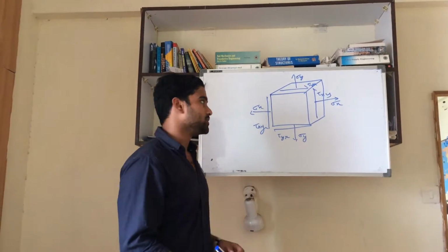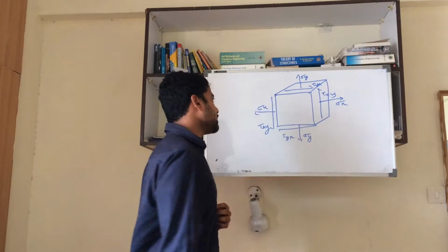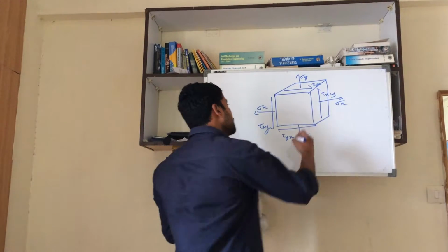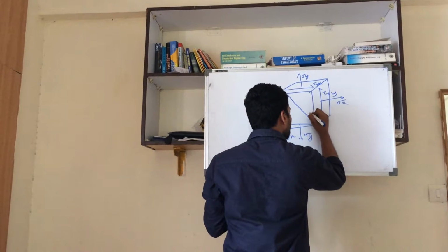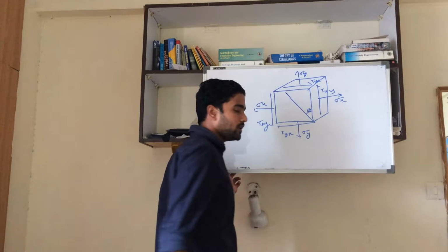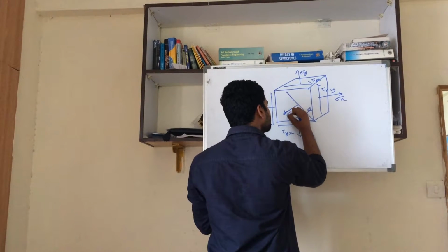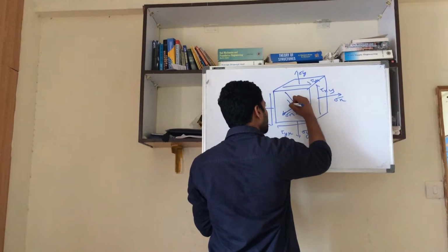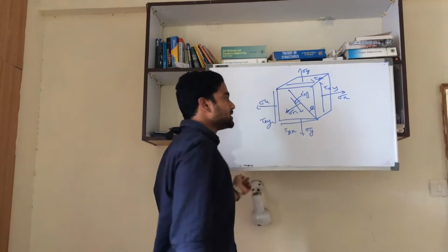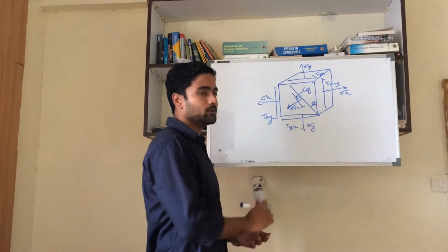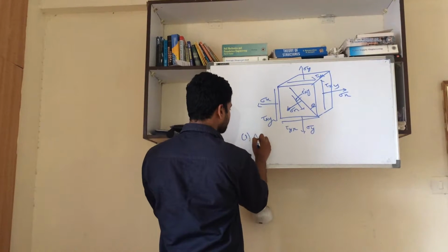What is stress transformation? If you have an element like this, we have to calculate the stresses in any other plane. Let us say the plane is making an angle theta, this is one of the planes, and we have to calculate the normal stress and shear stress on this plane. This can be done by two methods. First one is the analytical method.